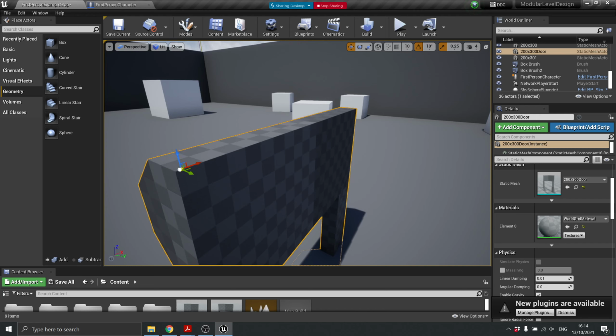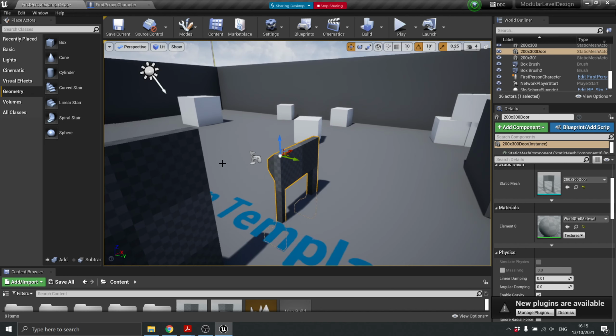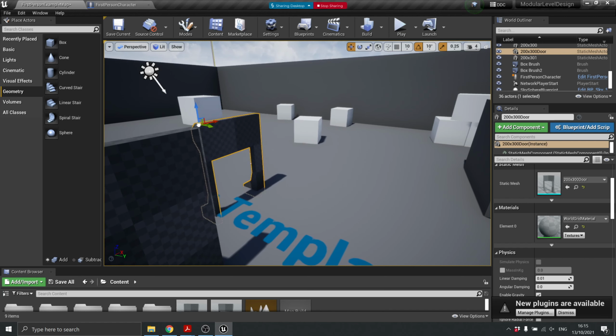So as I move this, I hold down Alt and V, Alt V and middle mouse button. It's a complex enough interaction. So you have to hover your cursor over the ball in the middle, hold down the middle mouse button, and Alt and V at the same time, and it will move this pivot point to the top. And then, when I'm moving this, if I want to align it with this object, I just use the left mouse button to drag this.